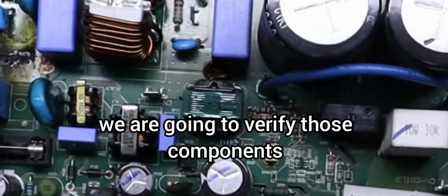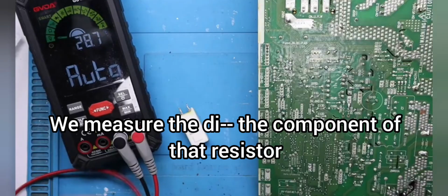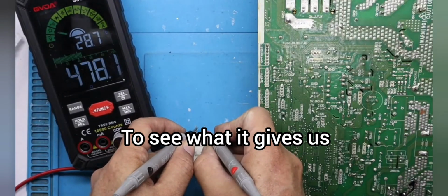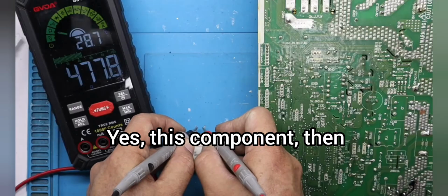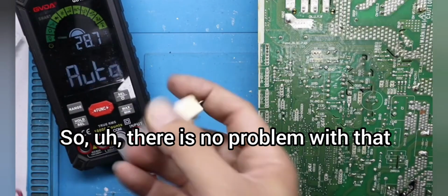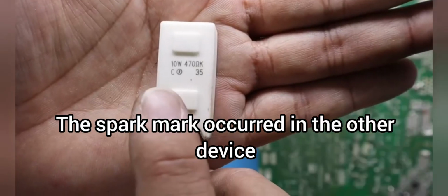So we are going to verify those components. We measure that resistor of 470 ohms to see what it gives us. 478 ohms. Yes, this component is good, it will work. So there is no problem with that. The spark mark occurred in the other device.